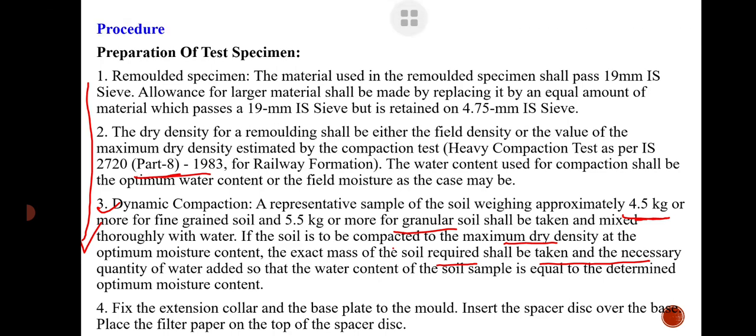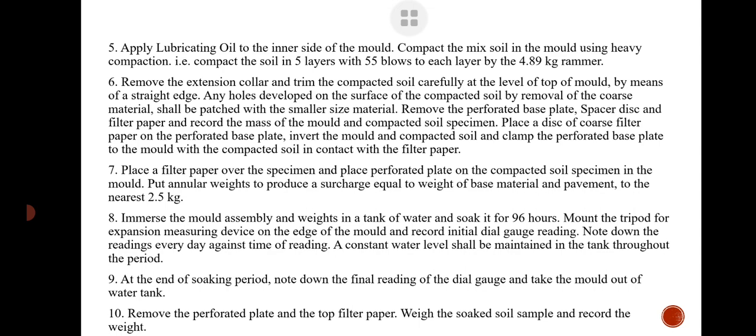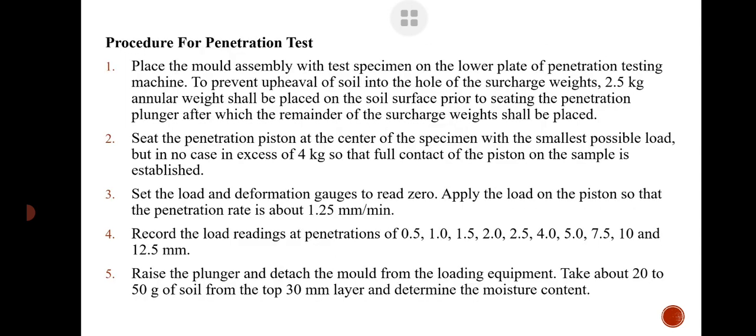Then, after preparation of the mold, we will place it on the mold of the modified compaction test or standard Proctor test. We will prepare that mold and test the soil specimen at its optimum moisture content and maximum dry density. Then we will come to the penetration test of the CBR test.